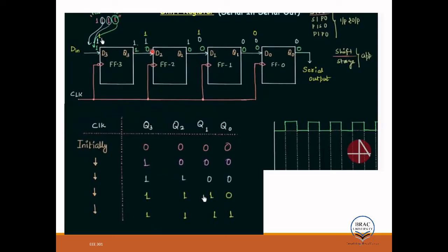Also, if you look at the output, this is our clock, and override initially was 0, later on it was high. So 0 means override is getting the priority. So in this region, that's why your Q is 1. But whenever override is high, it means your clock got activated, so it will work at the clock edge. So in the clock edge, it will be changing the state. So it becomes 0 to 1. Next clock edge, 1 to 0. Next clock edge,